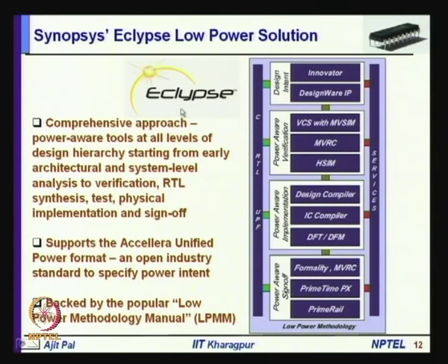and this Eclypse supports the Accellera unified power format, that is UPF that I mentioned, which is an open industry standard to specify power intent. And this is backed by the low power methodology manual. I have mentioned that low power methodology manual, which has been developed jointly by Synopsys and ARM together, and the various approaches which are proposed in this low power methodology manual have been adopted in Eclypse.